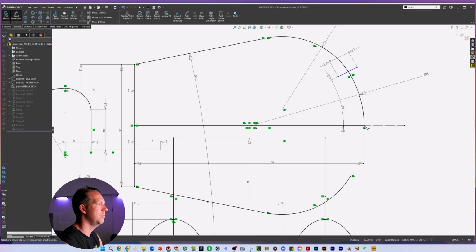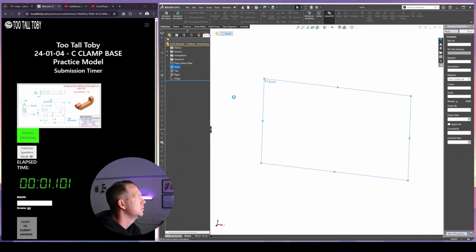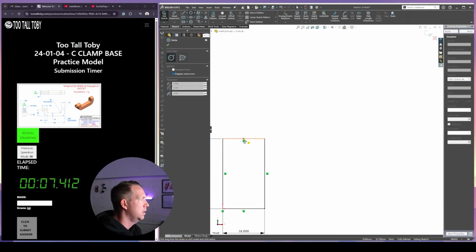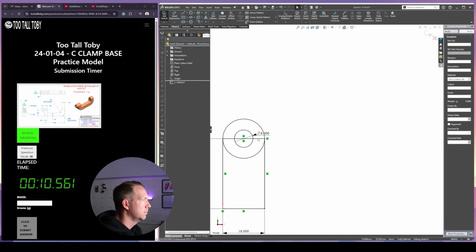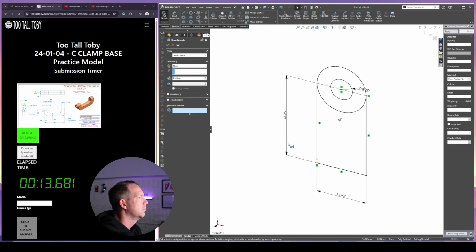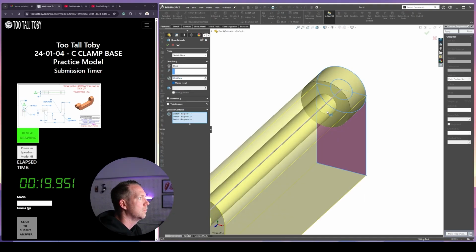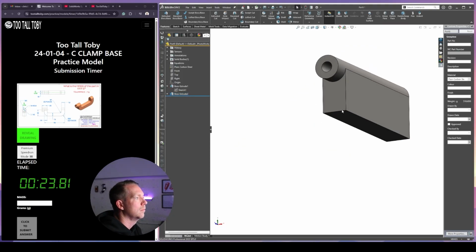Another big one was never using selection contours. I've always believed that trimming sketches down to a single contour was best practice. So I trimmed sketches down to the bare minimum every time. It worked, but it made my sketching workflow take longer than I would otherwise need. And for a long time, I never utilized the power of shared sketches between features.